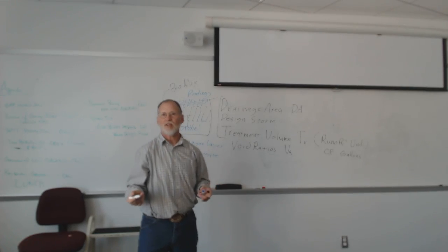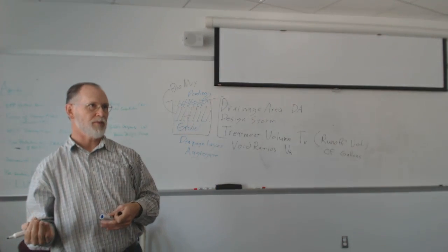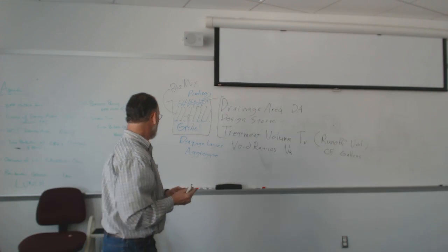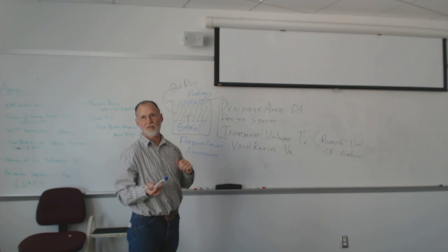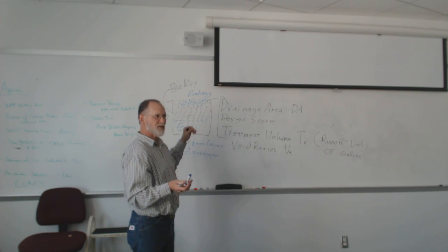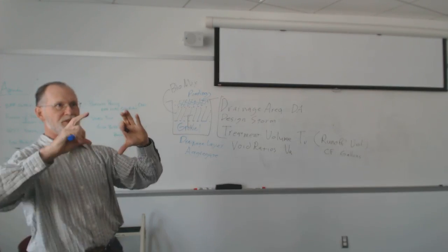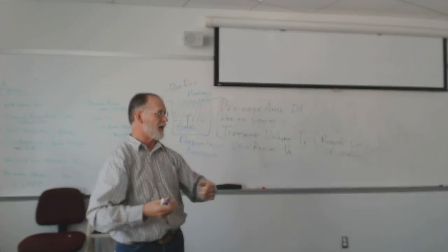That's just a measurement of how much open volume you are typically going to get when you've got an installed feature there, and then you're going to fill it up with water. With gravel, it's pretty easy to picture, but if you blow it up in your mind, instead of thinking about little bitty gravel, think about riprap, the stuff you see along the sides of the highway where the big pipes are dumping.